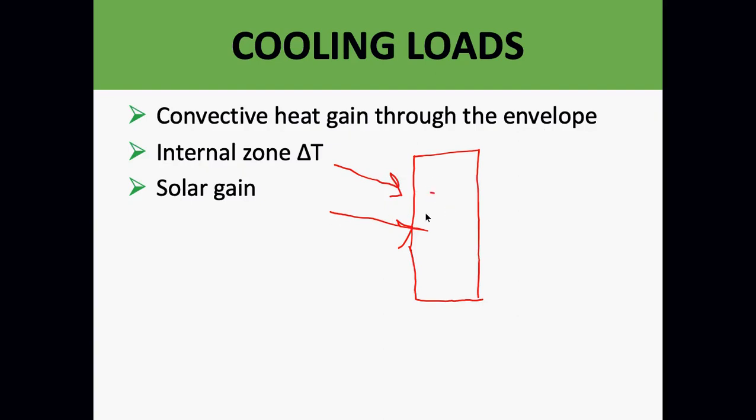It takes a while for the heat to make its way through this wall. So even though the sun is beating on that wall starting around 11 or 12 o'clock, the internal effects may not be felt until late in the afternoon, 1 or 2 o'clock, 3 o'clock, and that wall may still be radiating heat into the space until about 4 or 5 o'clock at night.